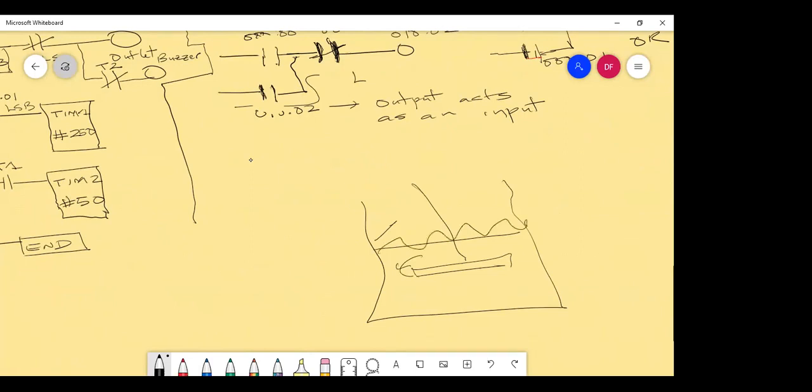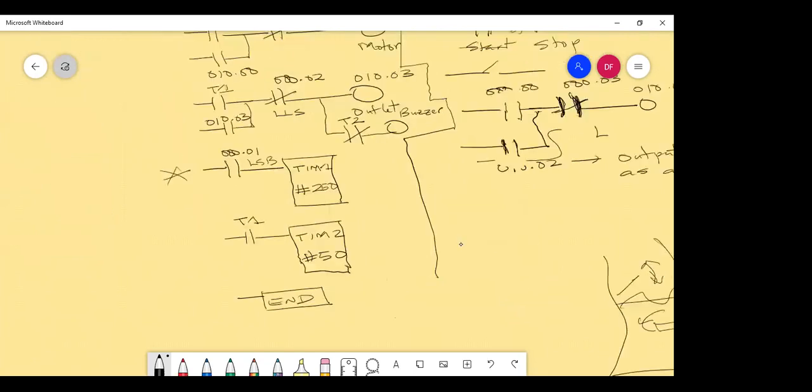So what happens is that your level switch starts to go up and down as the water agitates. So it kept on turning the timer on and off and on and off. So it messed up the whole entire program. It couldn't time anything, because it kept on just vacillating. So we had to go back to the program and change it.